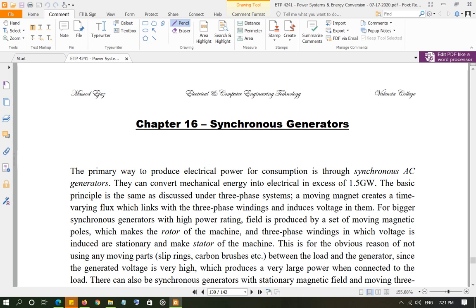So the end result is same. When the coil rotates, magnetic flux changes its value, which interacts with the windings that are not rotating, and the value still changes. And when the value of the flux changes, voltage is induced in those windings.